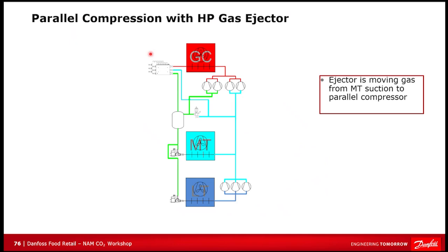And so this ejector is staging solenoids and cartridges inside of a block to allow that pressure to be maintained at the level we want it to. There's no extra logic from that standpoint, as far as additional pressure transducers or temp sensors that we need to install along with this. It's using our existing data and our existing sensor values to decide when to use this ejector and how much.